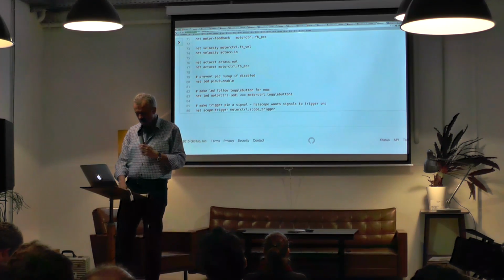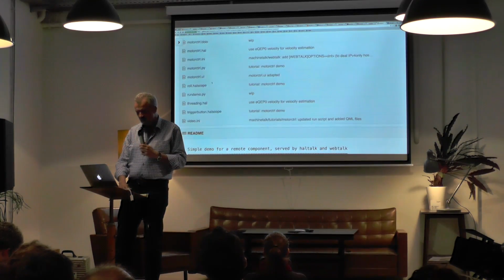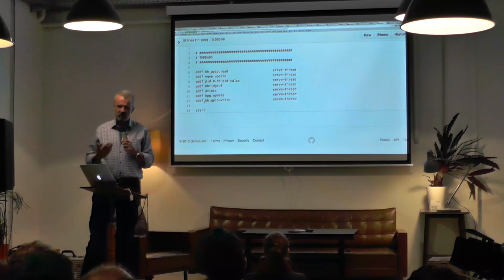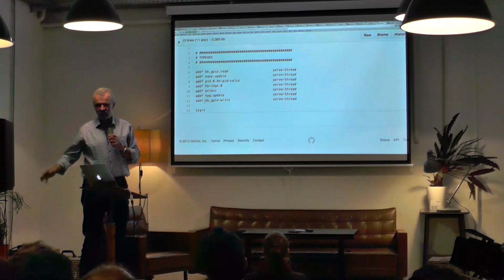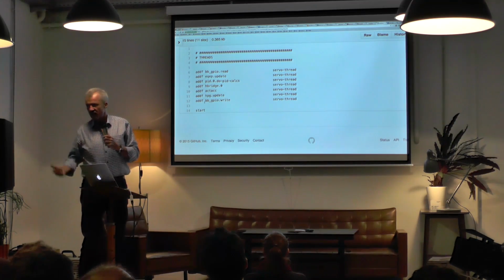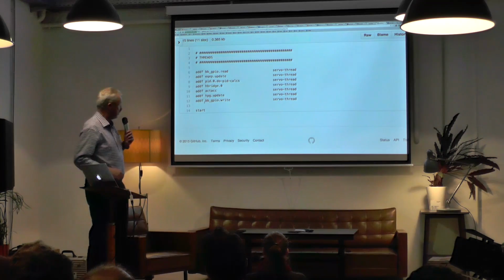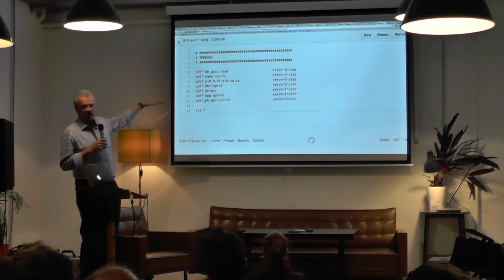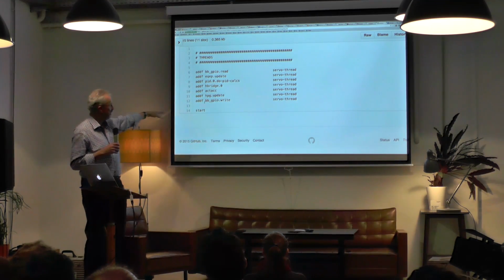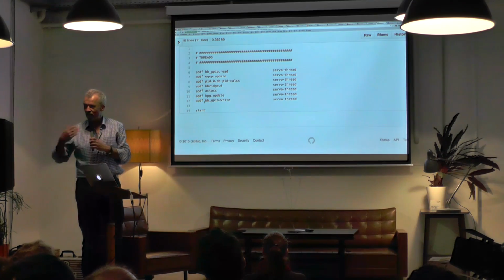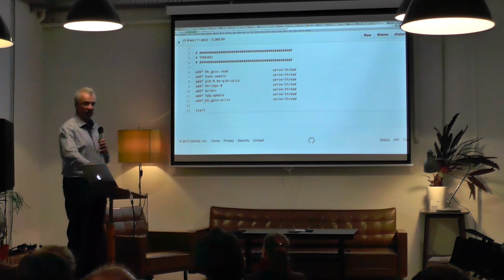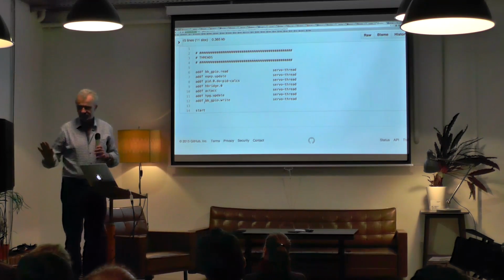And the third part is how the whole thing gets into action. That's by threaded execution. Threaded means, in that context, cyclic threads that run with a servo rate of 1 kilohertz, can go up to maybe 5 or so on floating point threads. You take the functions of each of the components and thread them onto a thread in turn, and then you start the execution. So that's how the periodic execution of that component system works. So everything which is on that demo is driven by these scripts. There was no C programming involved. That's it.